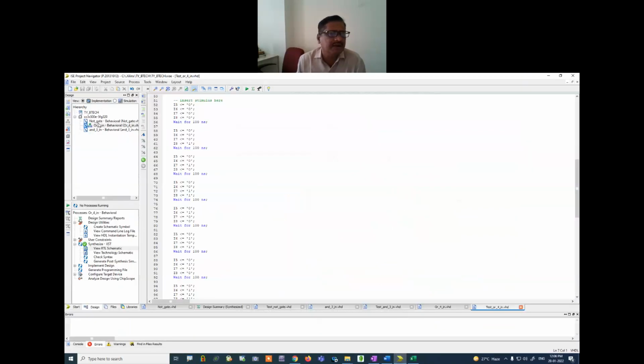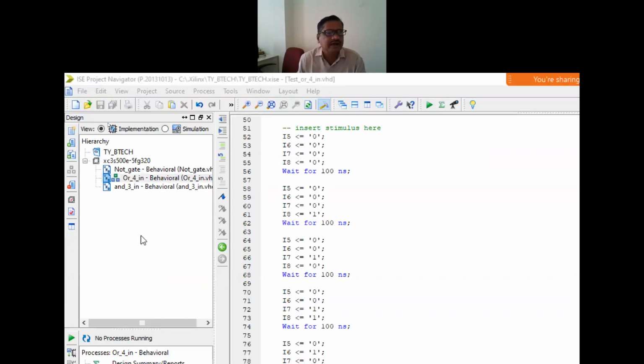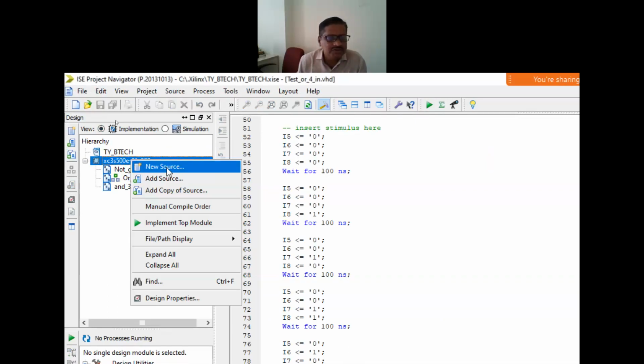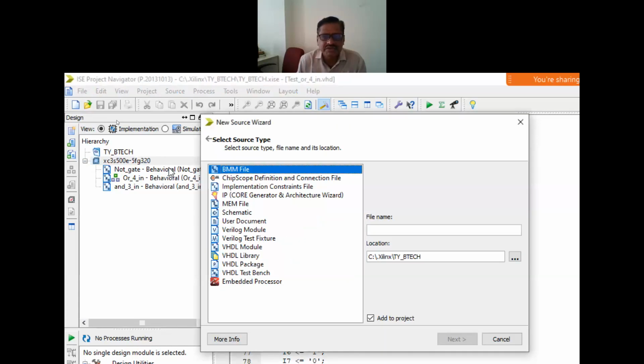I will come to the implementation part. If you are able to see here, I will click on this device and right click here. I will use the new source. This is a VHDL module, and I'm giving the name of the top module.